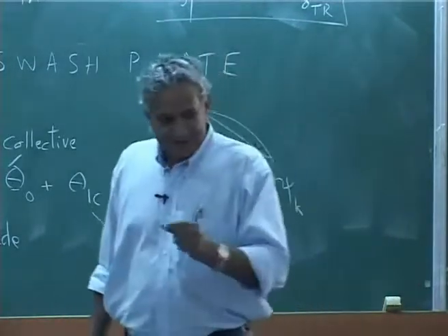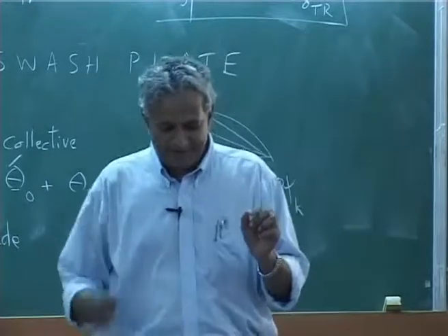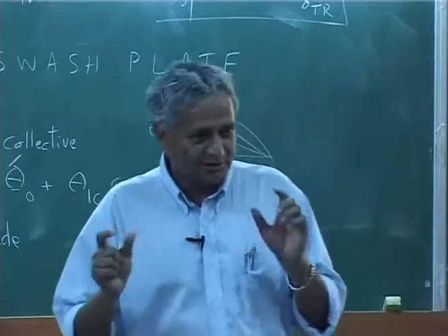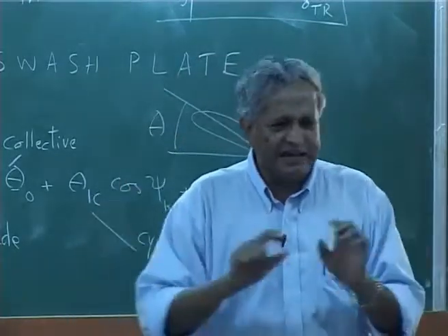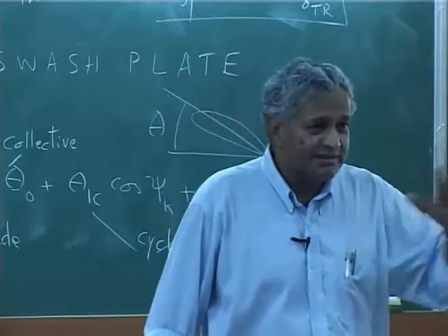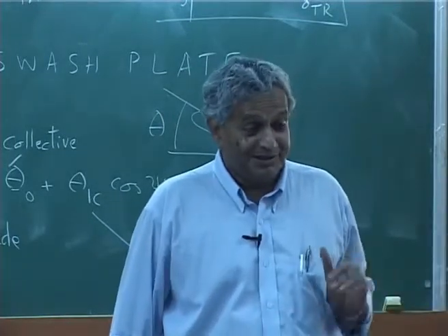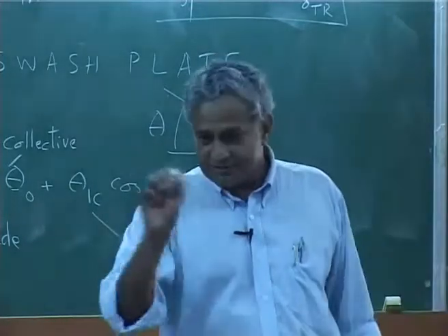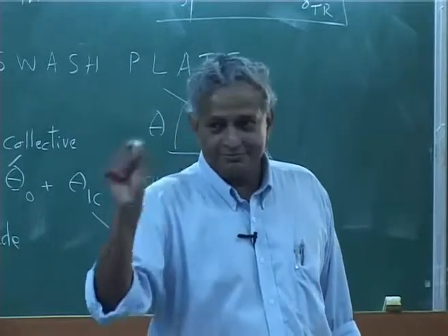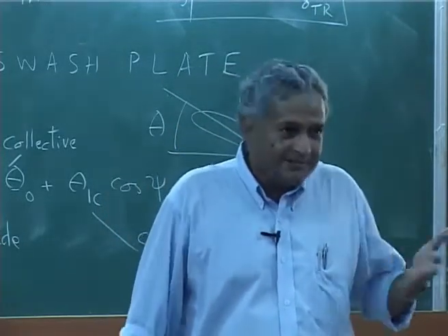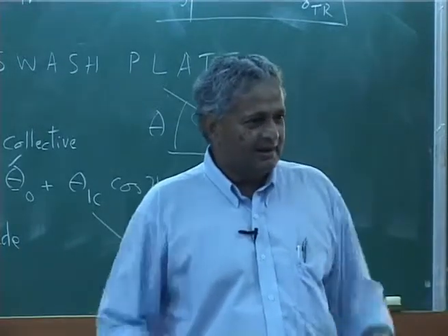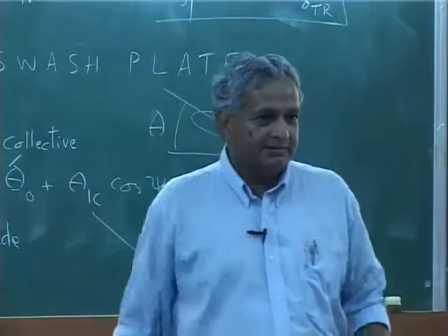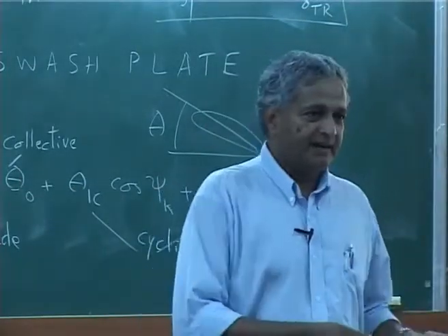Even today there is one small article that says people still do not know. They changed some metal to composite, identical, dynamically, meaning frequencies, everything is the same. But then when they put that rotor, you have a higher vibration. They said still we do not know why. So, these things happen: I change something, you think everything is identical, but then when you put it there, the measurement shows it has higher vibratory levels.